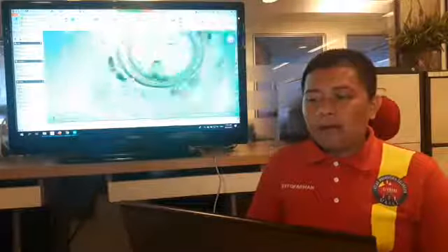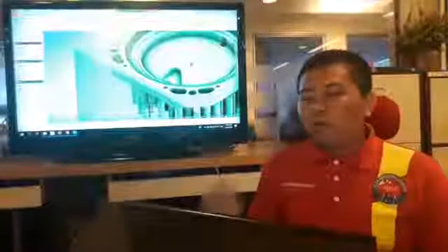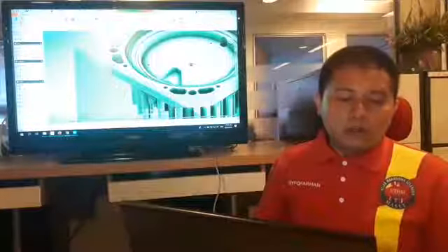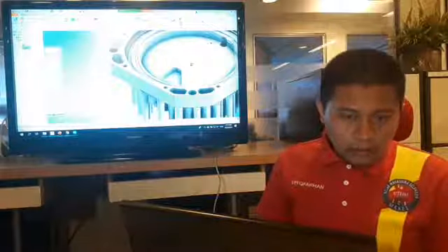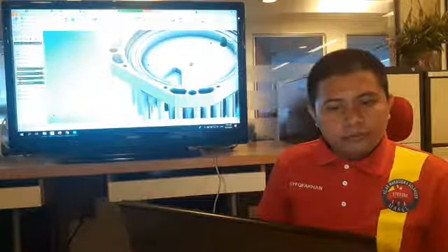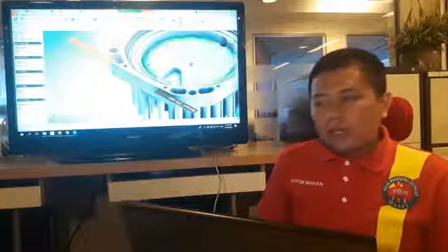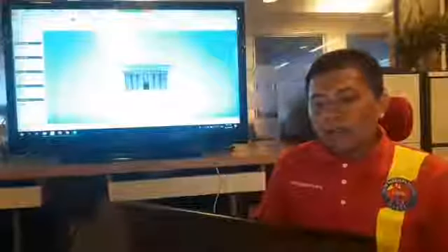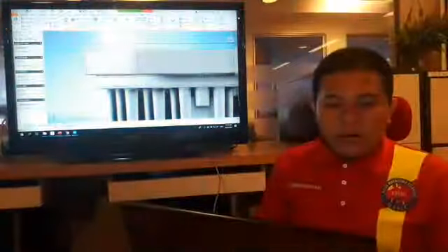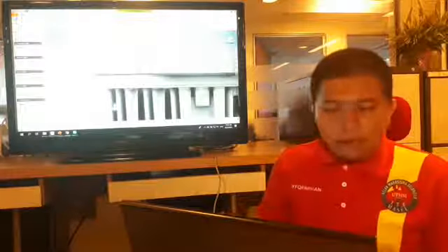For example, I want to make it go 0.1 mm depth. So I just go to here, slot, edit, go to stop. Sorry, go to stop. So I just want to make sure that my tools go a little bit down to touch the area that I want to cut.